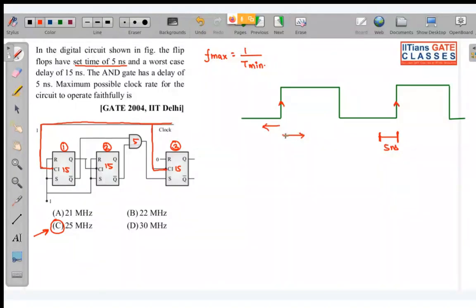So this would have been the concept of hold time if I start from here. So that is why I am starting from this clock edge. Because setup time relates to stabilization of input before the clock edge. So you can see this is 5 nanosecond. This should have stabilized. Now why I didn't start from here, I will tell you.